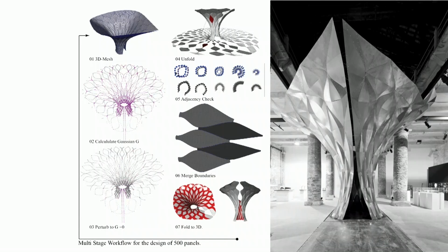And again, you can do it in paper and do a smaller one. In this case, we did this slightly more complicated process because we had to simultaneously unfold 400 panels and make sure that the boundaries align. So you couldn't unfold it once because then the next one is going to be affected. So you had to simultaneously ensure that all 400 panels have these conditions, that the faces are flat and the vertices, all those pink points, that the angles add up to 360.